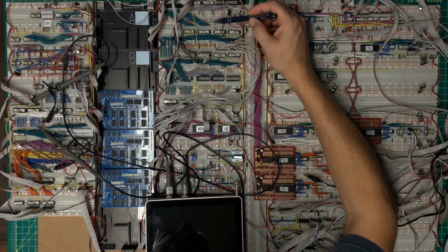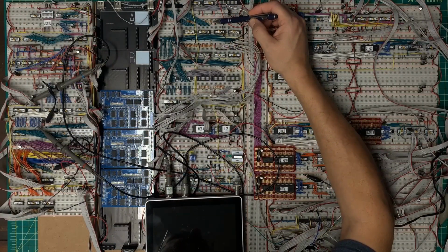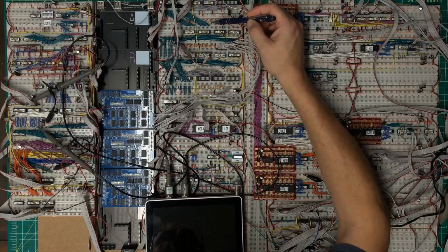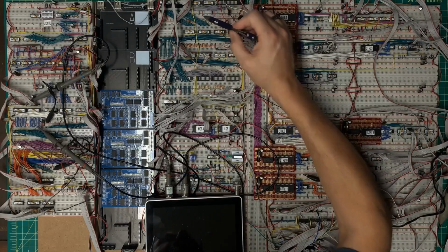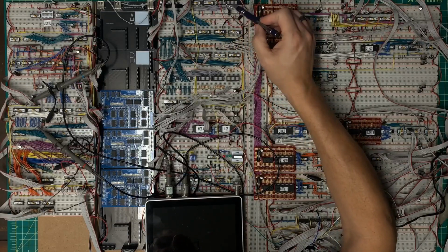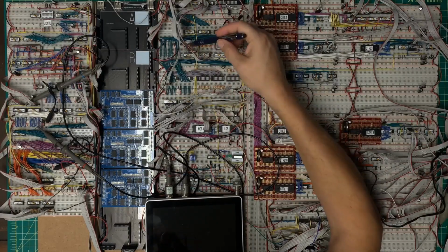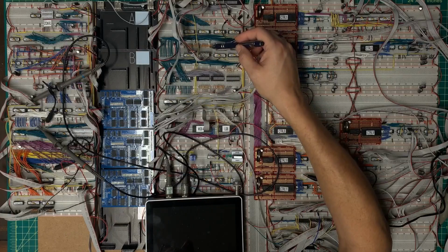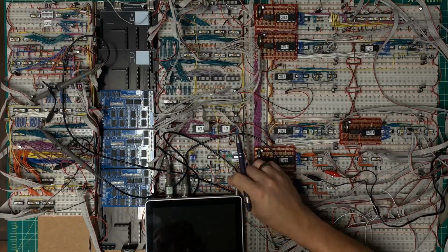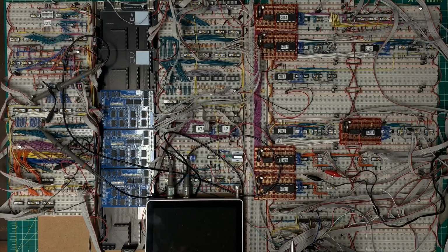I managed to replace these resistors with 10,000 ohm resistors. These are the pull downs associated with the instruction, which is what forces the no-op up here. And while I was at it, I went ahead and took care of the main bus. These pull downs are used on the main bus as the RZ pseudo register. So, okay, let's take a look now and see where we landed.